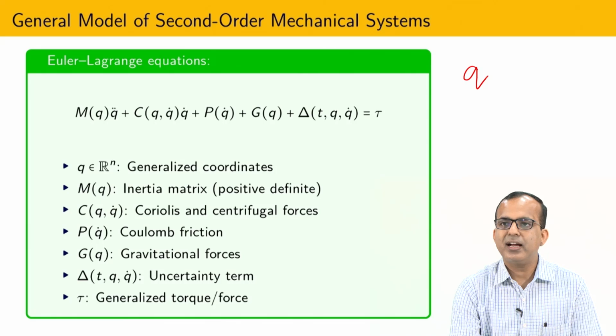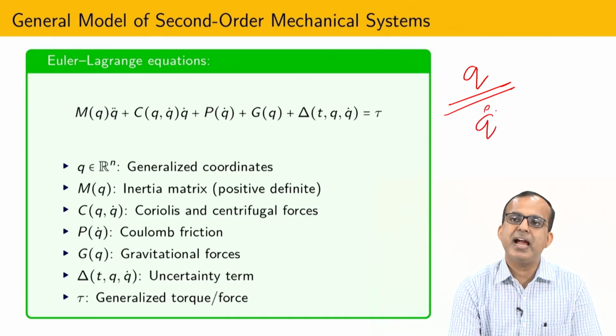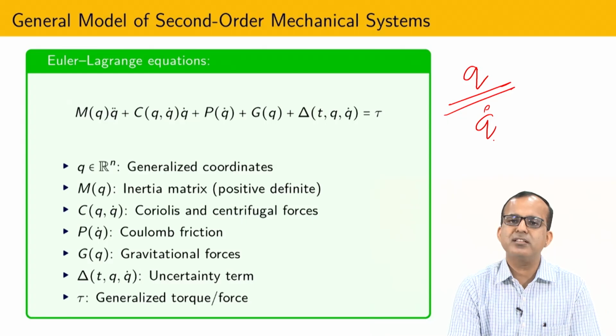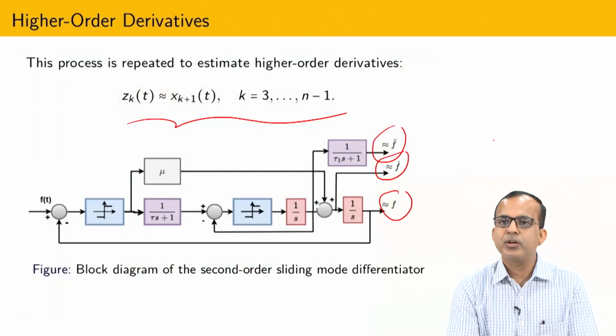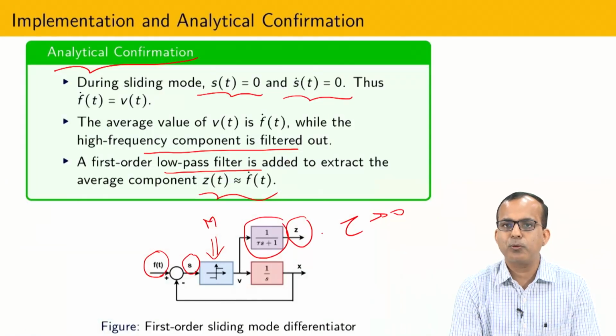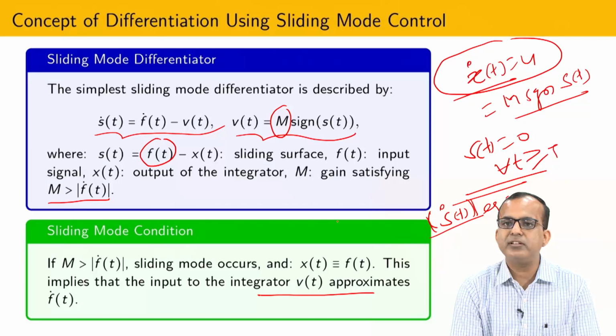If q is there, I will design some kind of differentiator based on Utkin's, or obviously high gain feedback. High gain feedback I am going to avoid, because that will just provide us asymptotic stability. But the differentiation process given by Professor Utkin, you can see is going to converge in finite time. Why? Because